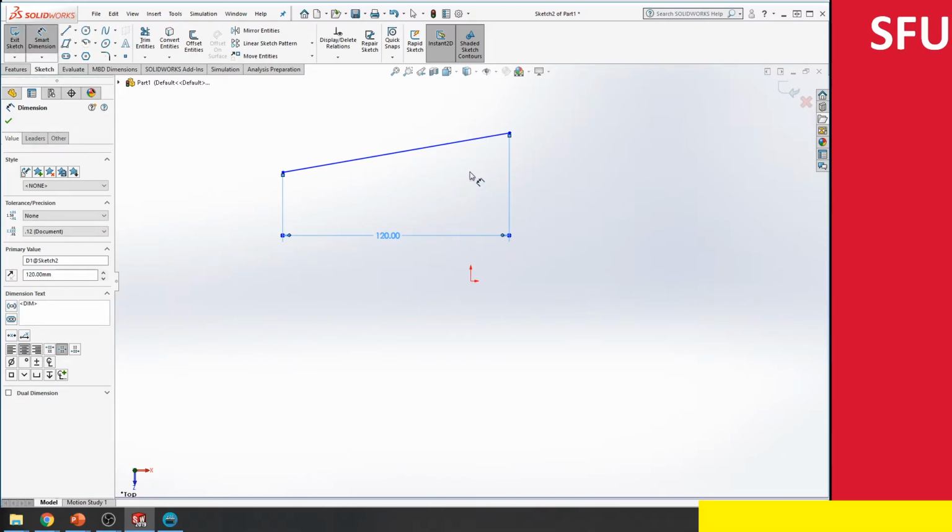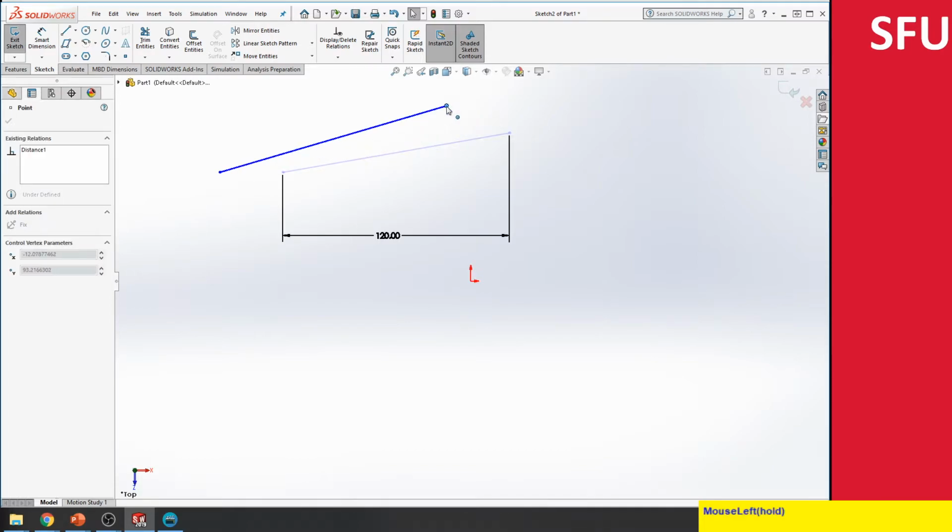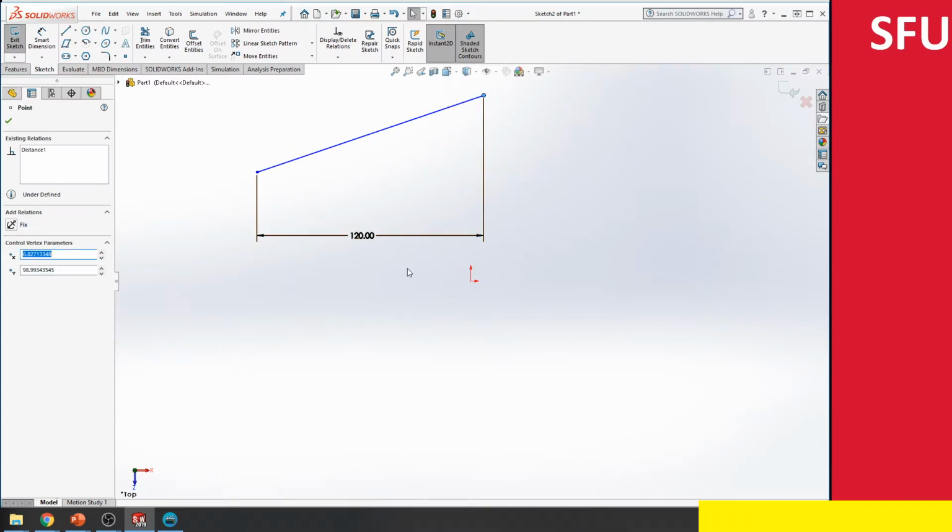What that means is if I try to move this point, notice that the horizontal length is fixed. If I try to move this point, it gets longer and shorter in the y direction, which changes the effective length, but the horizontal length is always fixed at 120. So this would be one type of dimensional constraint.